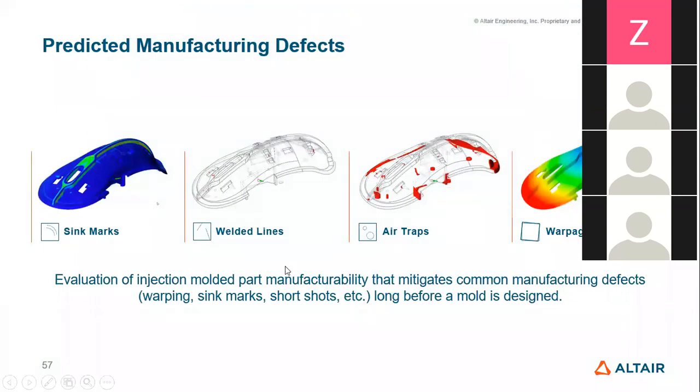So once you are done with the molding simulation, suppose you have simulated this mouse panel, and you have also designed the mouse panel, but in the designed component you don't have any manufacturing defect. But when you simulate this mouse panel, then it is filled with some air entrapment, some weld lines, some warpages. So I want to check the strength of this mouse panel for the simulated component.